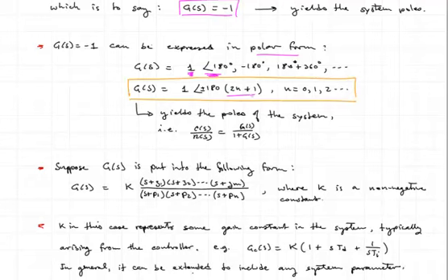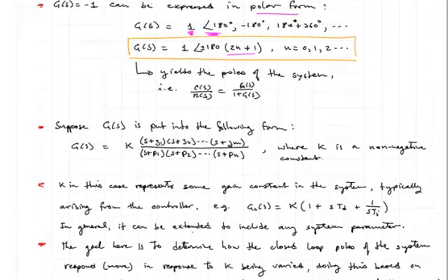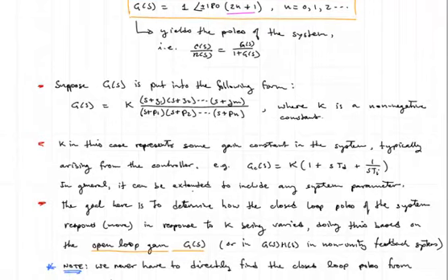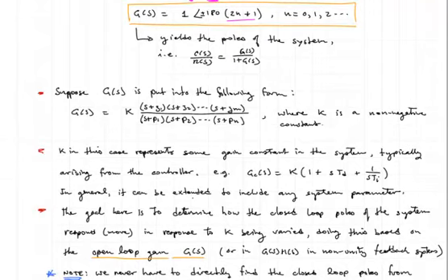Okay, so we now want to look at the particular form of G(s) and see where this new means of determining the closed loop poles can lead us, mainly finding where G(s), the open loop transfer function, has a magnitude of 1 and an angle of 180 degrees.